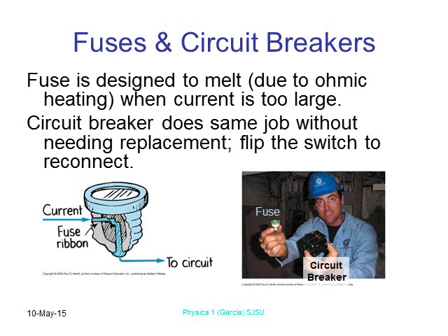All right, so your fuse is designed to melt, which is great, but then it's melted, and do you have another one, and do you run to the store to go get a fuse? Well, there's an even better idea, something called a circuit breaker. We tend to use these interchangeably because we'll say, run to the fuse box and flip the switch. It's a circuit breaker, but same idea. So in this case, when it overheats, it just pops the switch. And so you just run out to your fuse box, which is really a circuit breaker, and you flip it, and then the current can run through it. And again, that protects the houses that are now run in parallel and can draw too much current if you turn everything on.